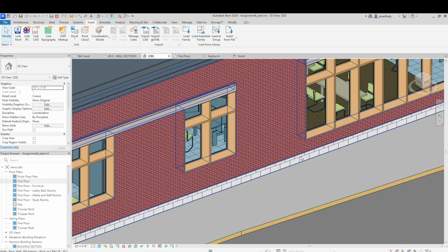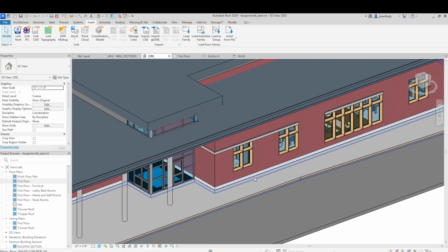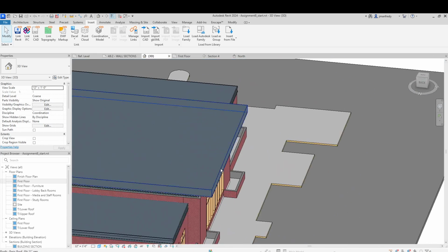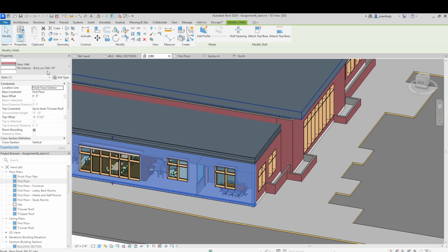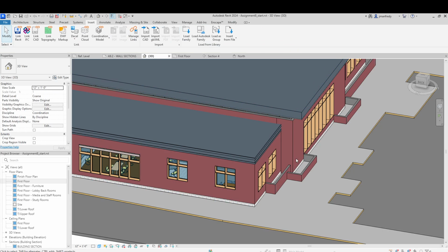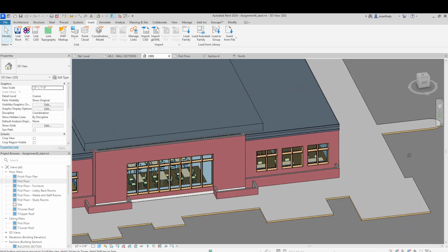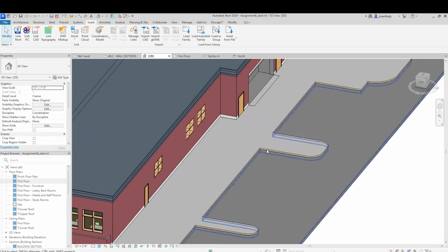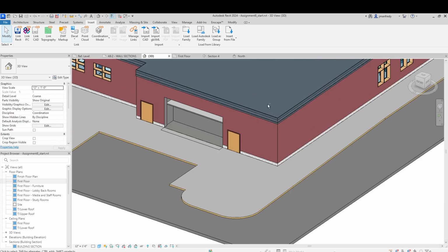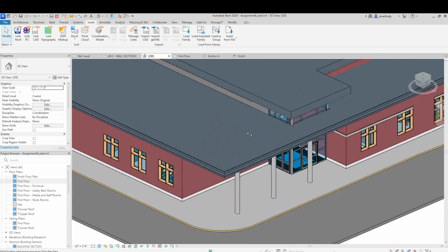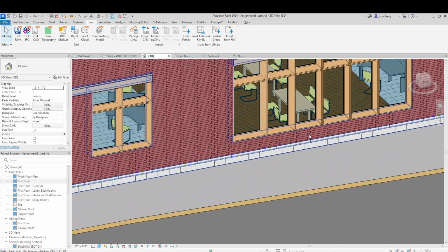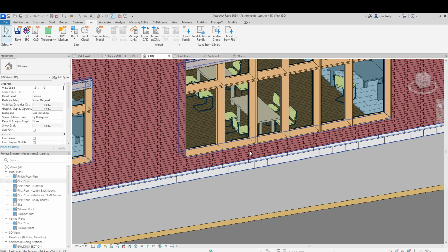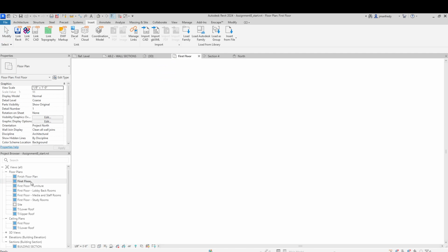It adds that detail continuously across the entire interior of that wall for all the wall types that are called this same identical name, CMU 18. Some of these did not change because they're different wall types. But you can see here, it goes across the vast majority of the walls here at a detail. This area here would need to be split face to change this material just in this location, not the rest of the remainder of the design.